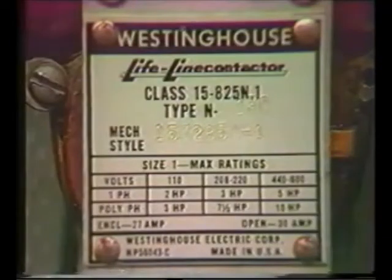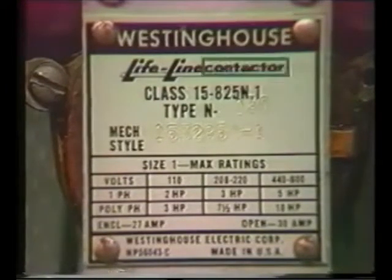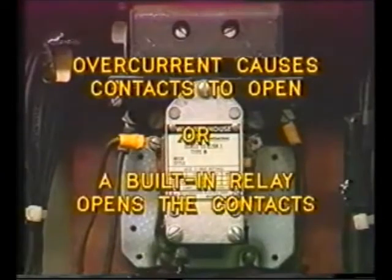Another type of protection frequently encountered at utilization voltage of, say, 480 volts is the direct acting contactor. In one common type, overcurrent causes thermal contacts to open the circuit. In another type, a built-in relay opens the contactor.